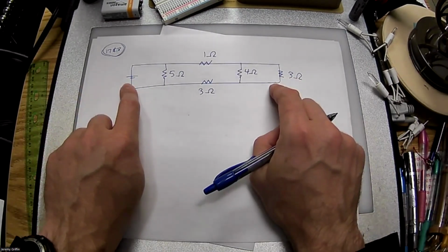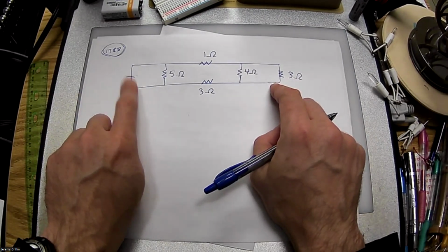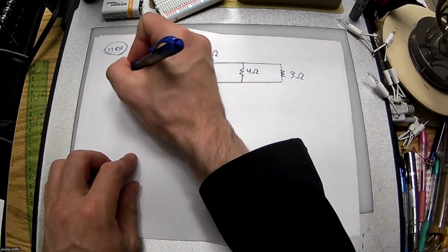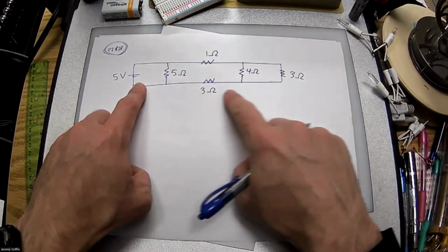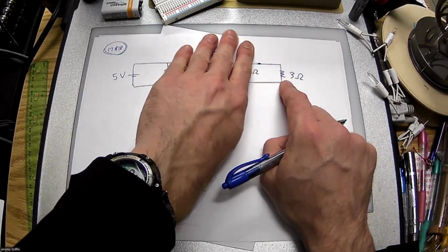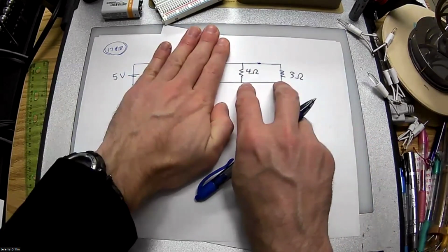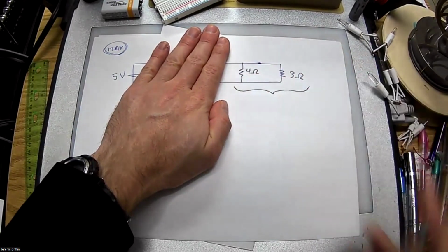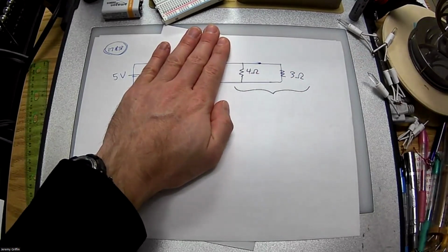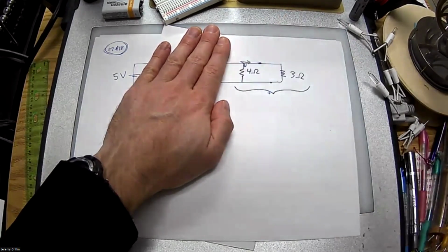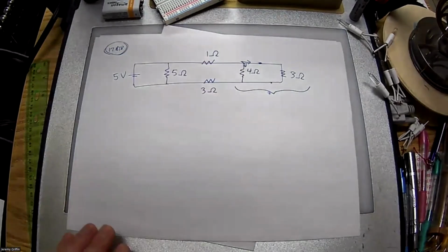So remember the process that I just told you guys. Find the voltage source, happens to be on the left side. We have 5 volts, that doesn't matter yet, but it'll matter later. I'm going to fly over to the opposite side of the circuit, which is this resistor, work my way back towards the source. Next, I run into this guy. So guys, these two resistors right here, is that a series or a parallel relationship? Parallel. You guys said parallel, right? Because I see a junction. I see the current's going to split. We push through both simultaneously.